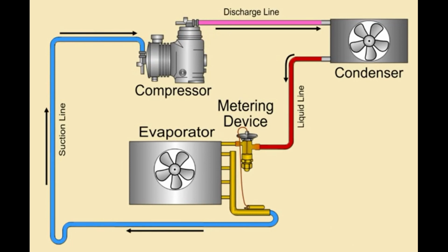There were cap tubes, pistons, and flow raters in different sizes for different tonnage of equipment, and they could only meter for that load amount. So it would have a heat load measurement for that system, and if you exceeded it or over-expanded the heat load, the AC system couldn't be efficient enough and it wouldn't cool the house. Your temperature in your house would go up.